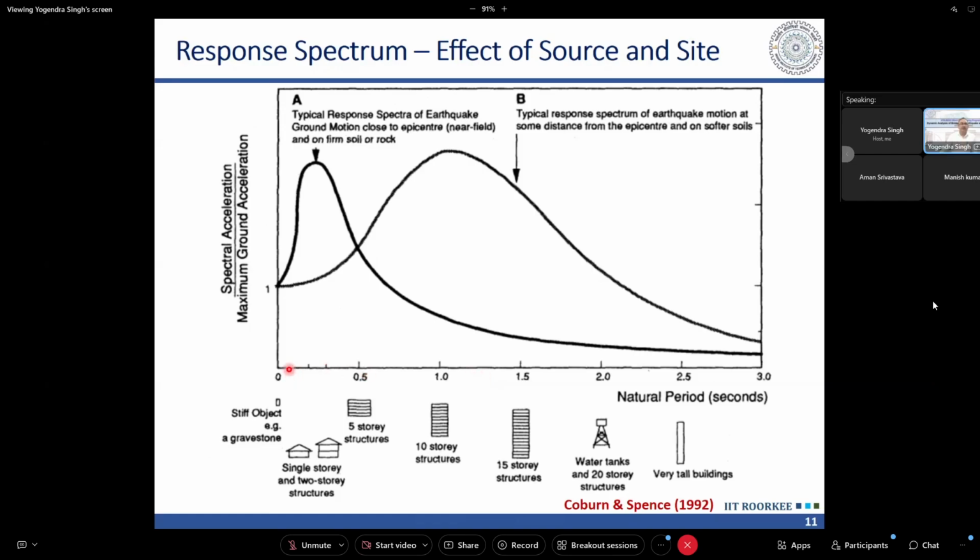And we can see here, this is also coinciding with the periods of different stories. So for example, this 0.5 second, or this 0.3 seconds where we are getting this peak, that will correspond to 3 stories. And this peak is somewhere between 10 to 15 stories. Roughly the period of the building you can take as 0.1 N.